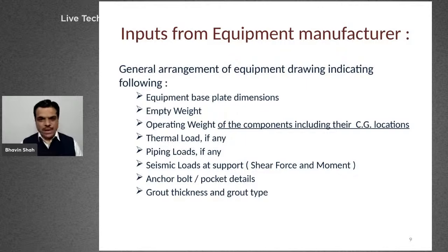A piping load, if any. Seismic load also is sometimes given, and sometimes we calculate it based on the mass of the equipment. Anchor bolt and pocket details need to be studied one by one, and that is a very important and very critical area, because ultimately the machine has to be fixed properly.